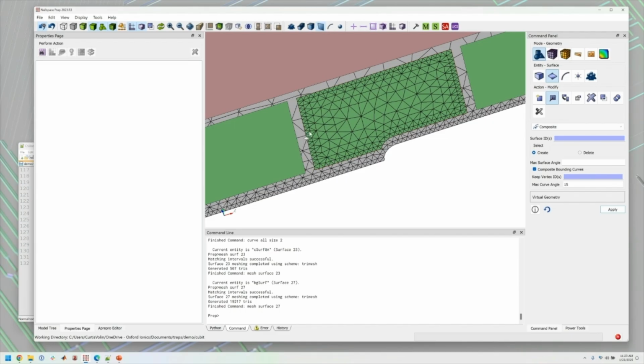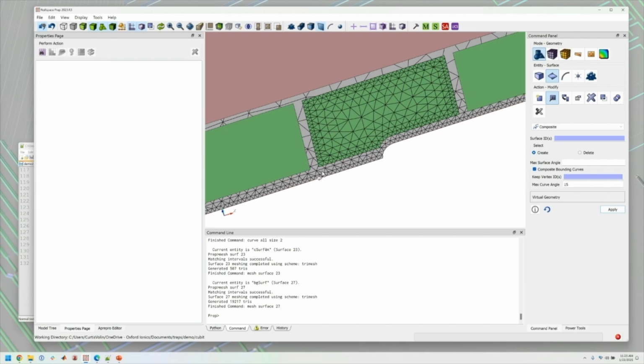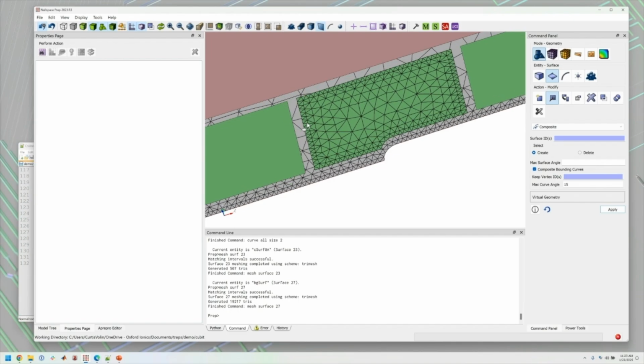And then tell it to make each successive triangle slightly larger. So I think the default in this case is 1.3 times. So each time it goes another row back, it makes the curves around the edge of the triangle 1.3 times larger. And so you have this kind of exponential growth in the triangle size. The same is happening on the ground plane below, right? As we have these curves and we have these tiny triangles, but these triangles are getting bigger all the way across here, so that they are much, much larger out here.